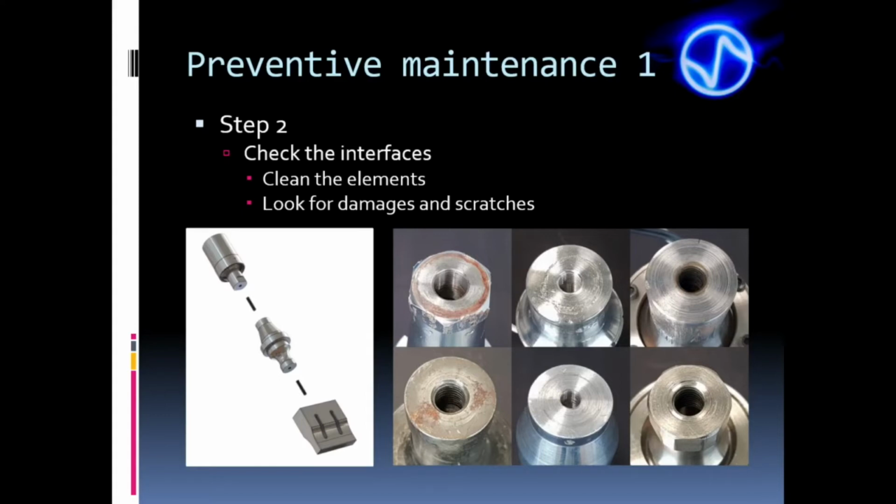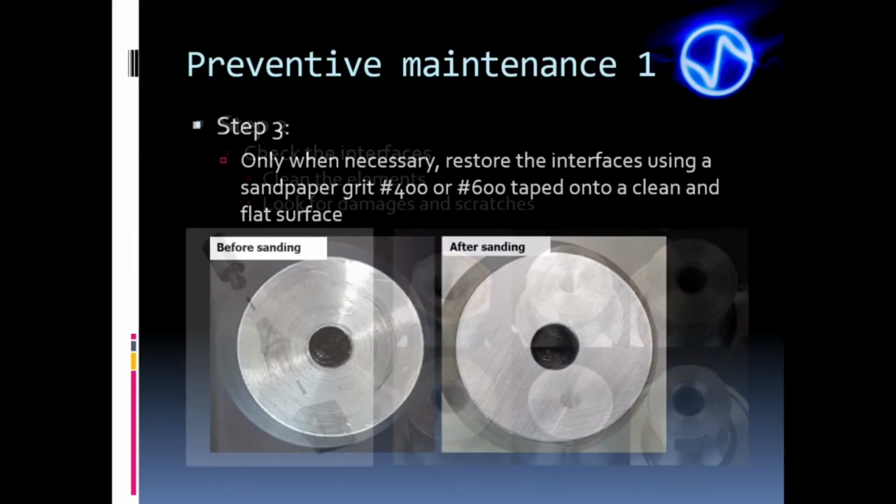However, as we learned previously, this damage and wear reduce the contact surface and decrease the ultrasound transmission efficiency at the joint. All of this reduces the coupling between the elements and causes stress and heat, affecting performance and frequency. So, what should we do when the acoustic stack elements' faces are worn out and grooved? We must restore the interfaces.